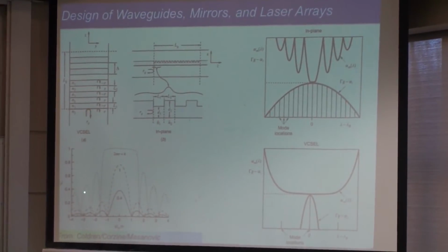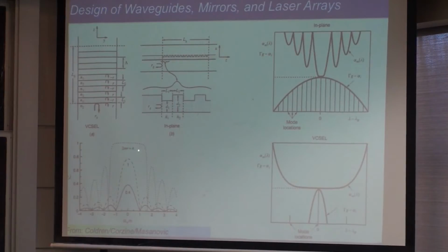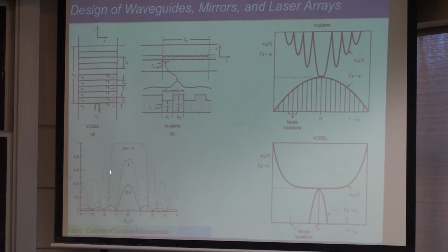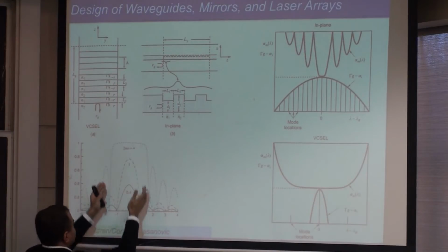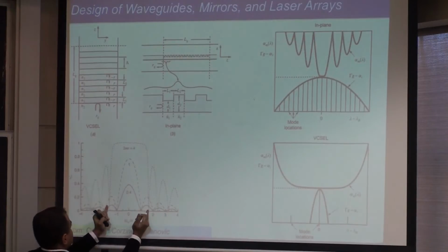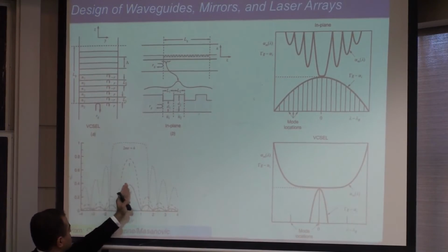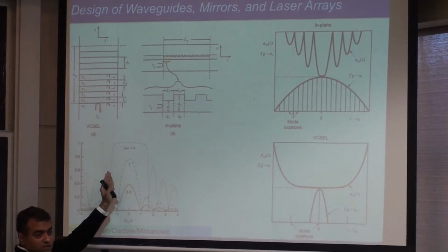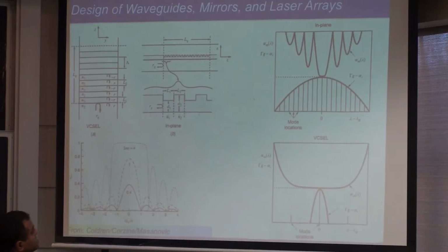The reflectivity spectrum of this Bragg reflector: it's not a mirror for all wavelengths. It's a mirror only for specific wavelengths. It has a reflectivity band over which it reflects very highly. But if you go outside that band, it can transmit almost 100%. So essentially, you want to choose a laser wavelength somewhere inside here so that you make use of the 100% reflection that you have designed it for.